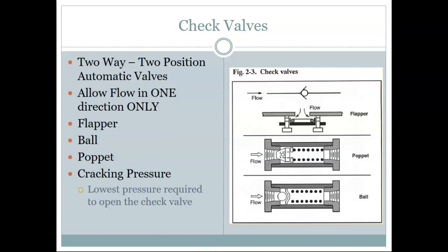All right. And if any of you have ever taken robotics with me, you know what cracking pressure is. It's where instead of just absolutely taking a handle and cranking it open, right? What are you supposed to do? You open it a little bit. Yeah, you ease it open. Why? Well, because you can have all sorts of nasty crud in a pipe and not know it.